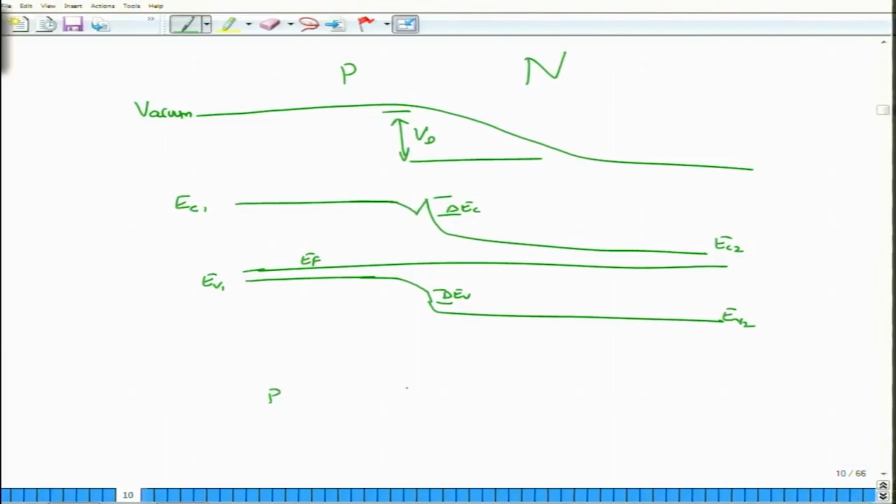But now if you put a P, an N, and an N, right. So, you had created a P and an N and an N. So, there was a spike here, and you now know that if you were to follow it up with an N junction, so let us see if we can follow it up with an N junction, there has to be a spike, right. So, from the small N region it has to go down initially, then rise up and then fall down, well, not exactly, so this is the falling down. So, this is the triangular well that is created, this is the well that is created over here. Okay. So, these are the two wells created.